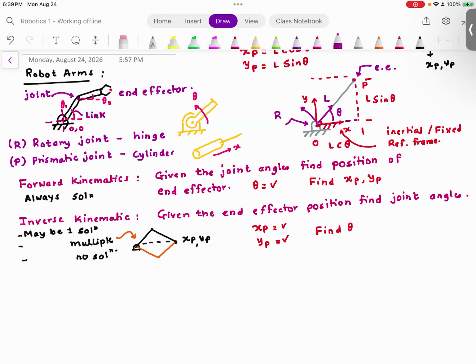Everyone understood this? So X, Y, Z. The next thing that you should keep in mind is the rotations. The rotation is positive if you curl your right hand in the direction of rotation, and if your thumb is pointing in the positive direction, positive X, positive Y, or positive Z, that rotation is positive.